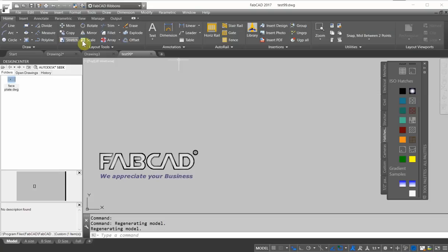So, using the draw commands in here, you can use an arc to draw a scroll. You can use a polyline to draw a scroll, because Polyline has an arc option. And then you have splines, and there's a spline fit and a spline CV. So, we'll do all three of them. We'll start with the arc.